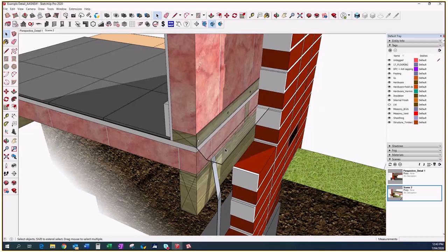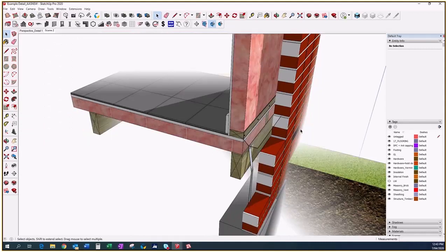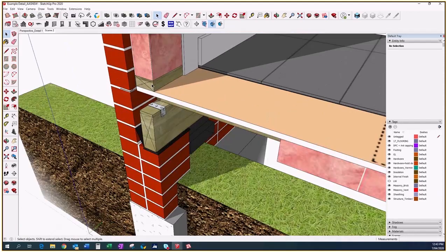So inside of SketchUp at any time, you can not only create a layer by what it is, masonry versus hardware, footings, flooring, whatever it may be, but you can also have your entity info, so that when you are drawing in there, it will tell you IFC categories, it will tell you what kind of brick, what size joist you're using. All of that metadata is essentially what BIM is. And SketchUp does that. It just doesn't do it in any forcible way. It's really up to you to create your own system.